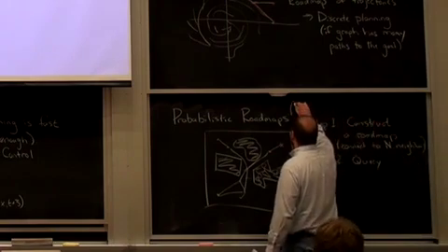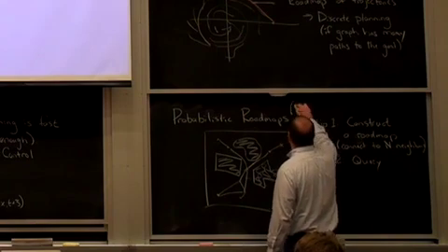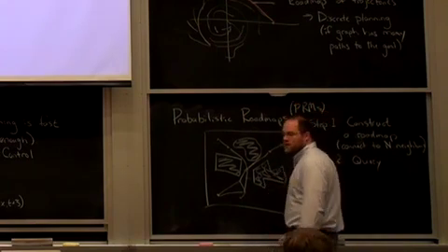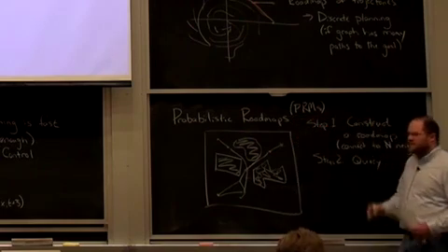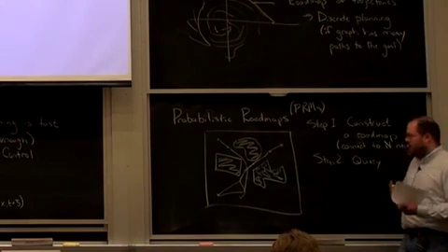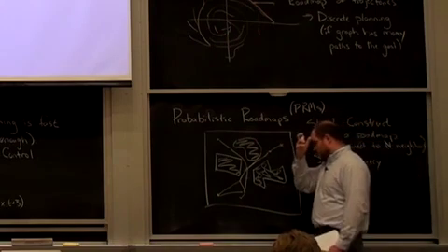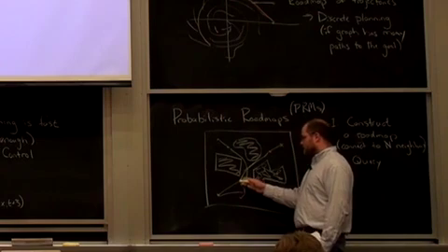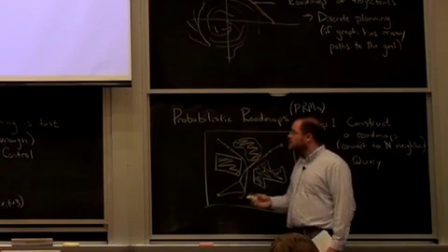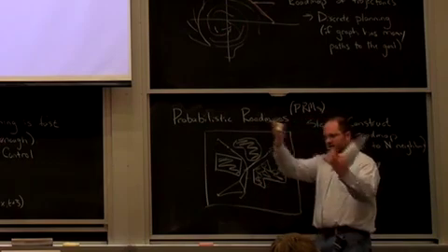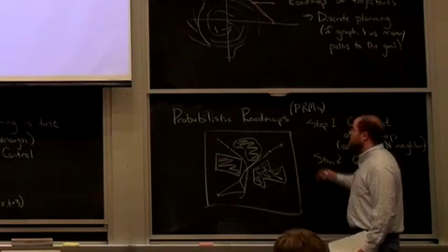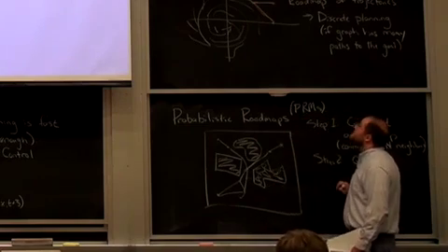The rapidly exploring randomized trees go by RRTs. These go by PRMs, probabilistic roadmaps. A lot of people seem to think that they're intellectual competitors with RRTs, and I don't think that they really are. I think the RRT guys would just say, well, you just use an RRT to make the connections, and the roadmap is still a very good idea. And I think RRTs sort of effectively make roadmaps. So I think they're very harmonious ideas.